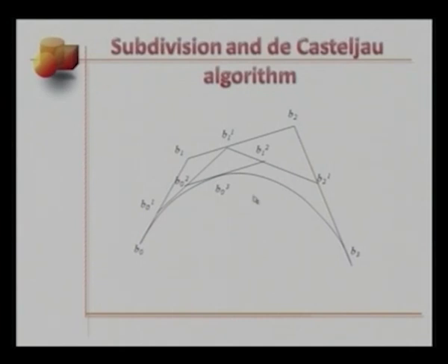You would have observed that this Bezier curve is tangent to the last segment here, joining V02 and V12. And also V03 would lie on the Bezier curve. I'm emphasizing these line segments, joining V0, V01, V01, V02, and V02, V03.